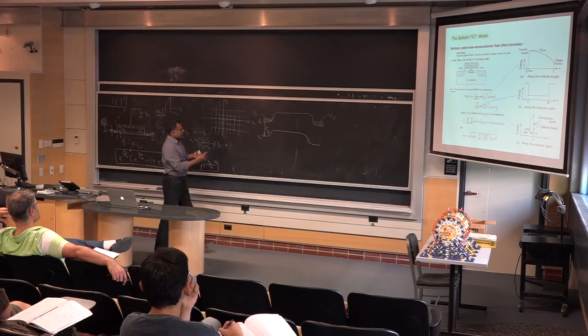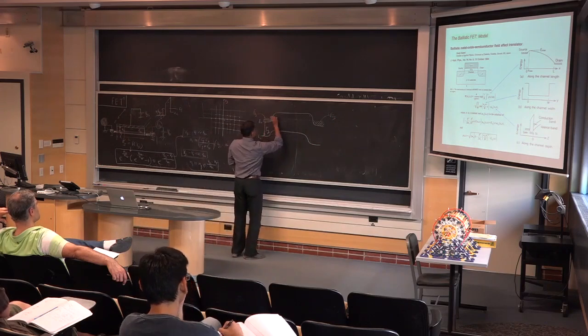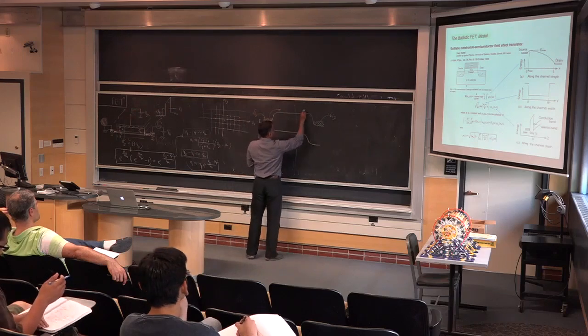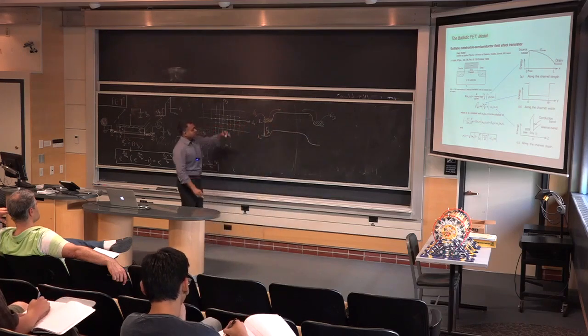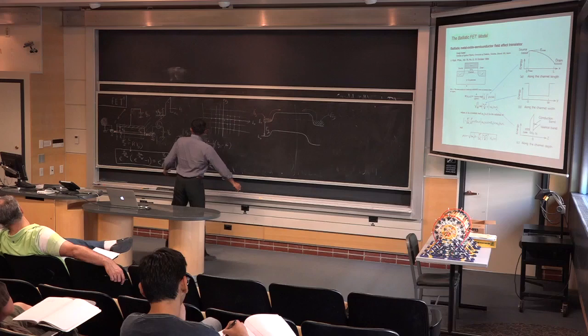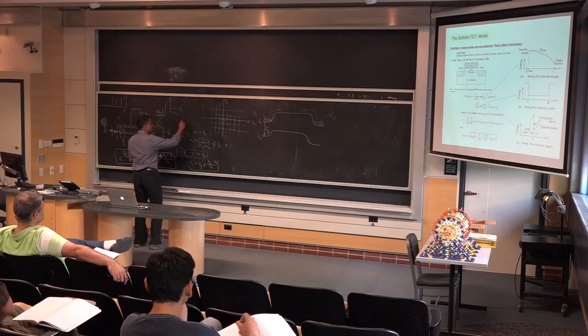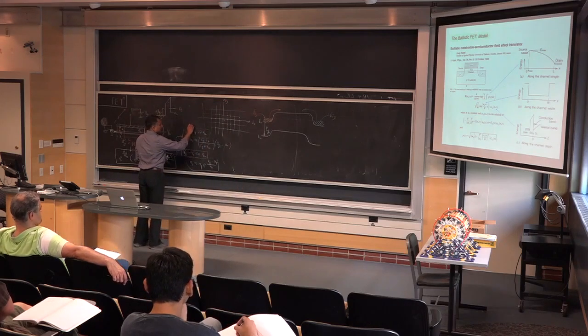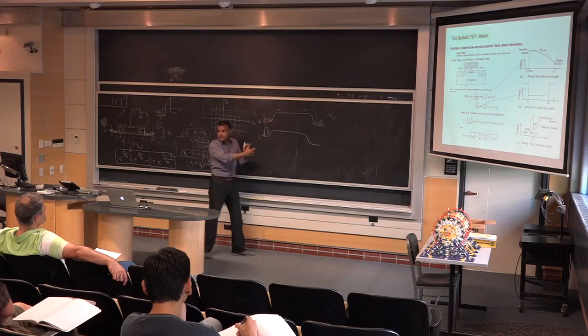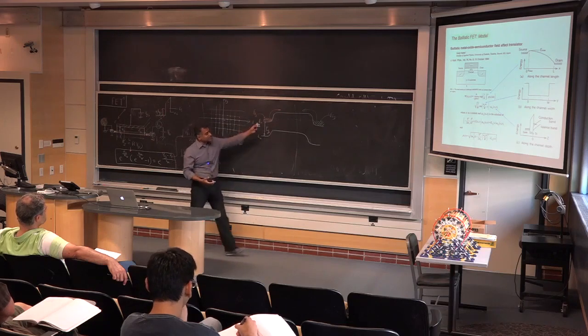And as a result, there are electrons getting injected from here, this way, into the channel, and from here this way into the channel, and there's a certain barrier height, and that barrier height is being controlled by the gate. That's the whole game, right? As the gate becomes more and more on, this barrier height is going down, and you're injecting more and more carriers from both sides. And the carrier density in the channel is increasing exponentially.